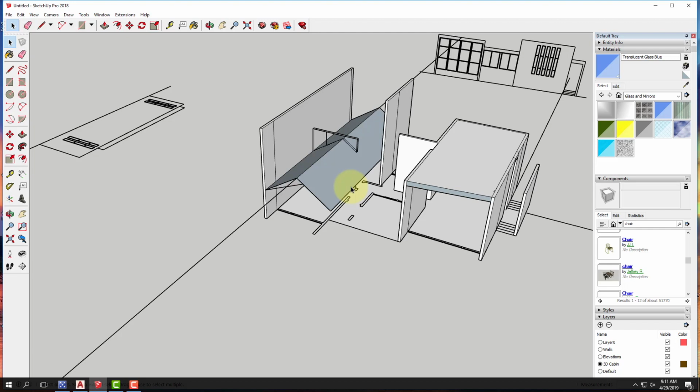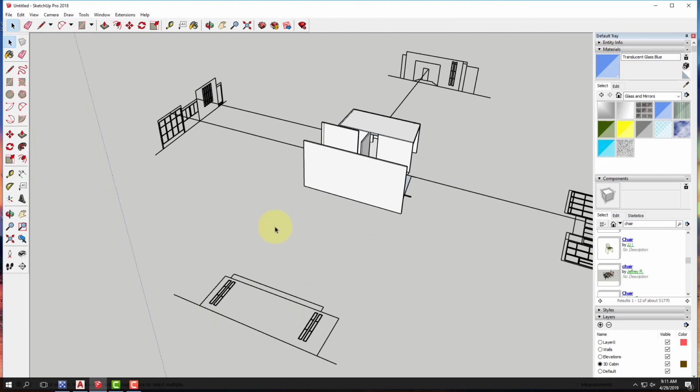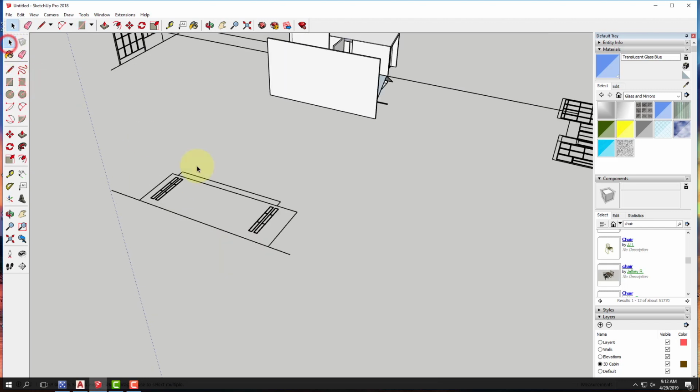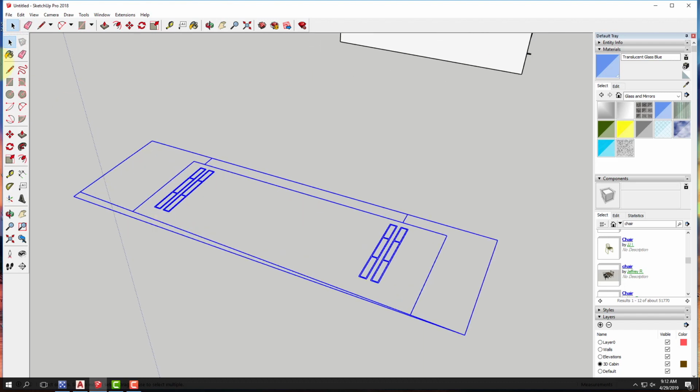Can you just show how to rotate the elevation here? Sure. Happy to. So on this elevation view here, I'm going to create a little cheater object because SketchUp doesn't work as nicely as something like Rhino with a 3D rotation. If I went with the object and went straight to rotate, I can't get the protractor to stand up on edge. So the easiest strategy there is to give yourself some kind of a little 3D object. And a box is the easiest one to create.